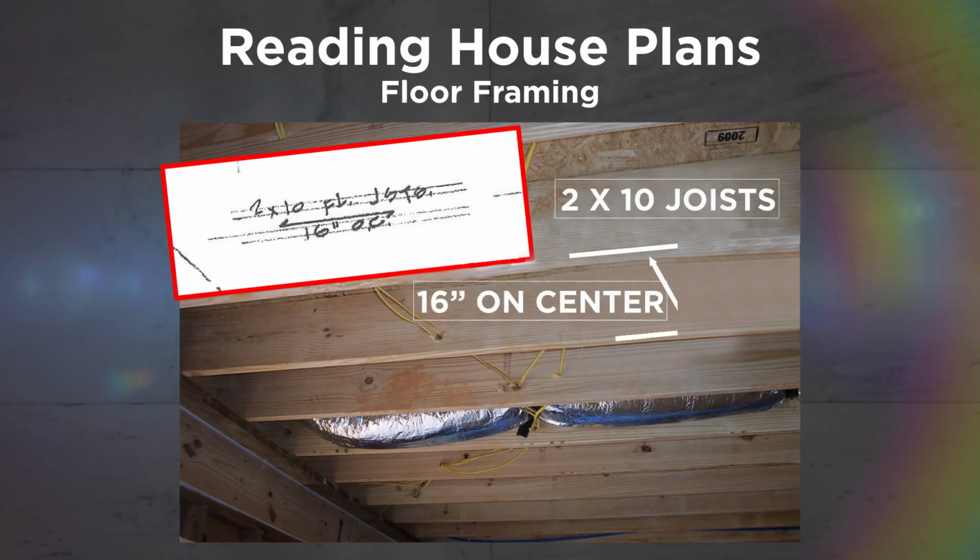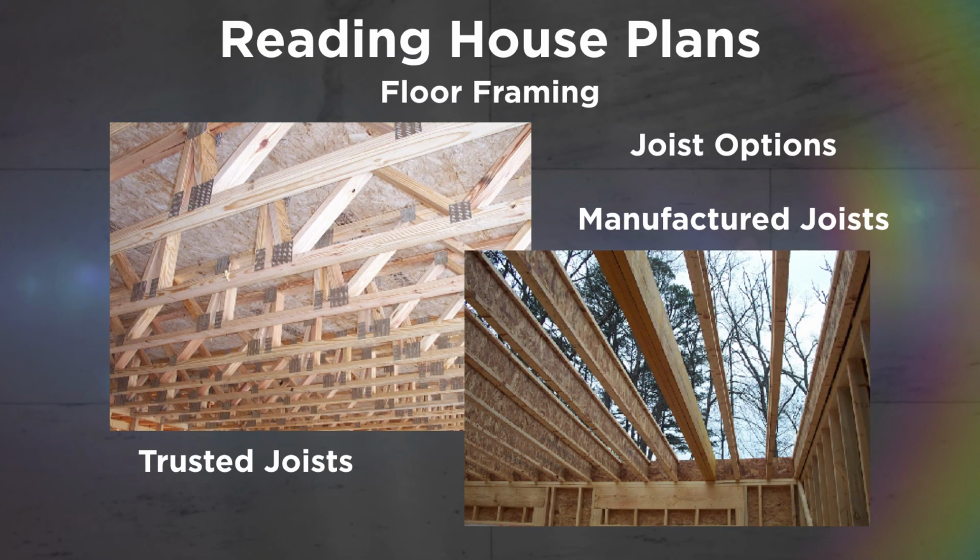Here's the notation aligned with the picture of the floor joists. We see the notation 2 by 10, an arrow, and then 16-inch OC, which means the joists are 16 inches apart, center of joist to center of joist. 2 other types of joists used in home construction are the trussed joist and manufactured joist. These may cost a little more than the floor joist used in our plan. However, the span is often greater, and in case of the trussed joist, our load-bearing wall in the middle of the basement may not be necessary.